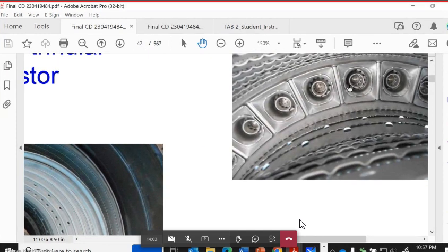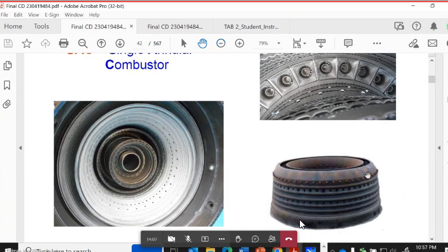The only downfall is, if you noticed on here, this is a circle. And so my shaft from my high pressure compressor is coming through here, going out, and my high pressure turbine is on the other side. And so the only way to get a circle off of here would be to pull the shaft apart. Remember, this shaft is in two pieces.